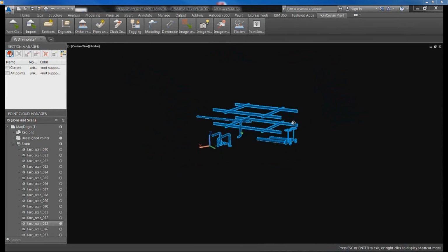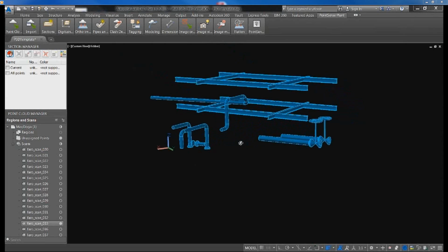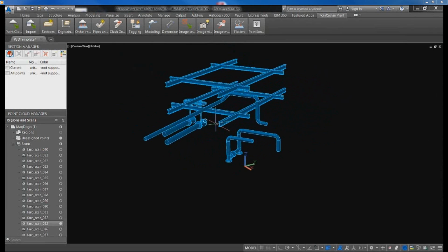Again, this is real time. It took all of those and applied them to a single centerline grid. Now I should mention that each steel member has the ability for you to shift which part of that is being designated as the centerline. For example, a lot of people want to put it on top of steel, or maybe you want to have it in the absolute center of a channel piece. You can do that.